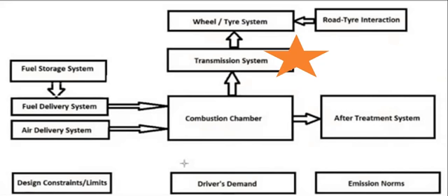Though any storage tank for fuel may be so called, the term is typically applied to the part of an engine subsystem in which the fuel is stored and propelled or released into an engine. And next comes the fuel delivery system. The fuel delivery system consists of all the components which supply the engine with fuel. This includes the tank itself, all the lines, one or more fuel filters, a fuel pump, and the fuel metering components.